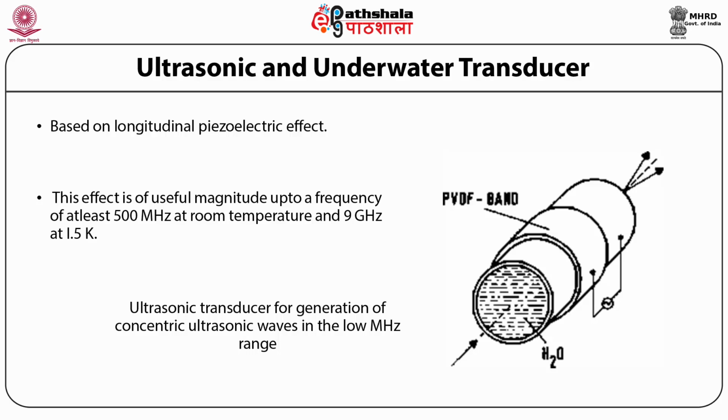As shown in this figure, a cylindrical PVDF sheet is properly mounted to generate ultrasonic concentric waves, for example, in water. Similar transducers have been the subject of extensive theoretical and experimental studies with such quantities as insertion and dielectric losses investigated. Possible applications of such transducers are the measurement of ultra-low attenuation of liquids, the detection of particles or bubbles in flowing liquids, and non-destructive testing.